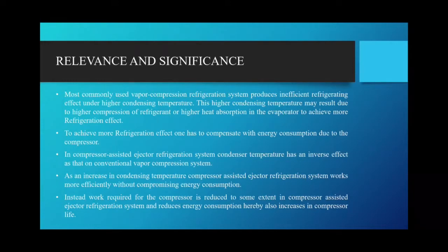This higher condensing temperature may result from higher compression of refrigerant or higher heat absorption in the evaporator to achieve more refrigeration effect. In order to achieve a higher refrigeration effect, one has to bear the loss of energy consumption due to the compressor work.